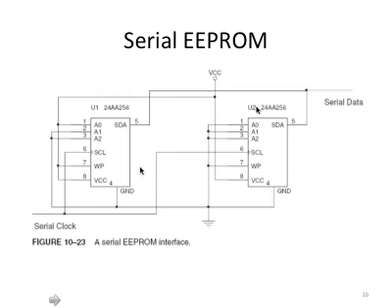This A0, A1, A2, you can see they appear on both of them, but the way we connect these chips is different. For the one on the left, we connect A0 to the VCC. A1 and A2 are connected to ground. Okay?